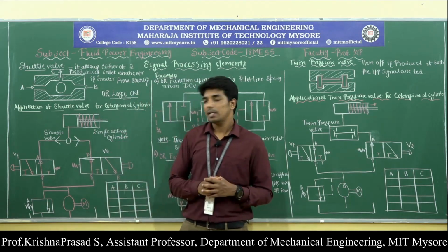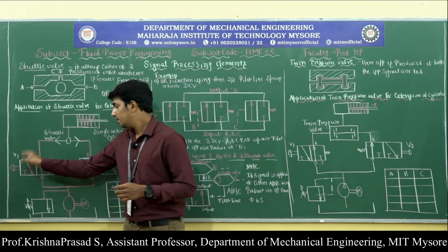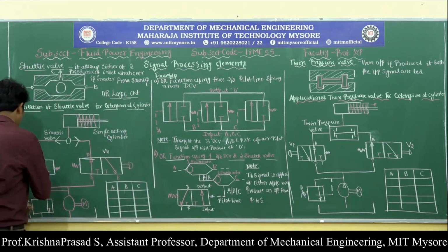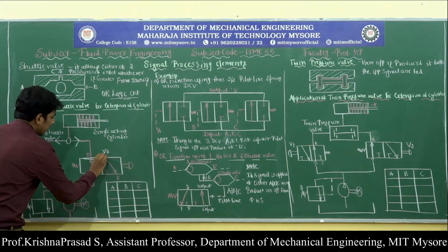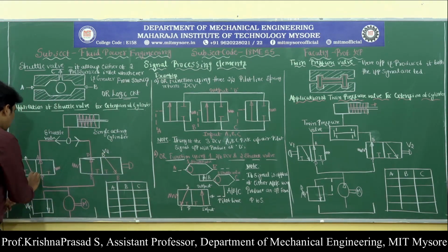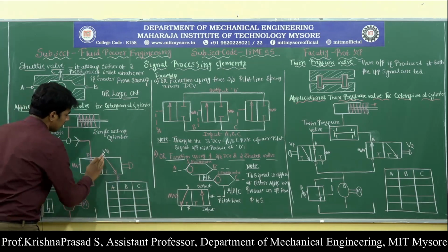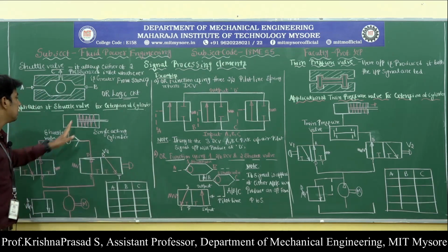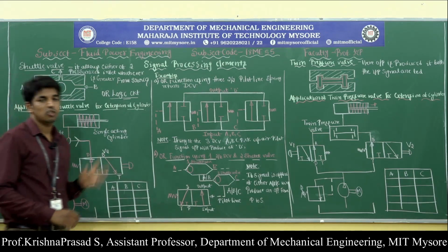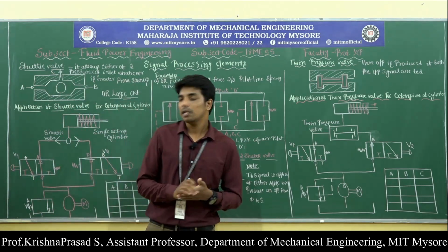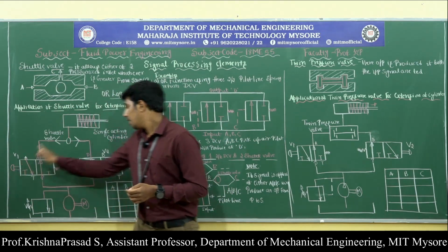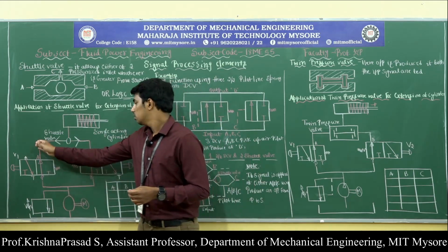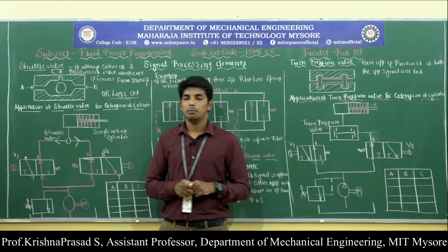During the normal condition, in the direction control valve, the outlet ports A and B are connected to the tank port T, and the cylinder will be in the retracted position. So, this is the normal condition.